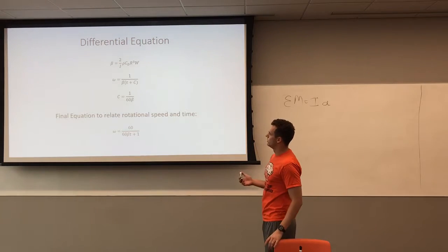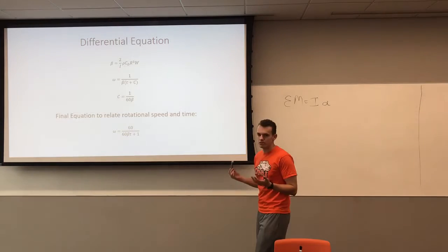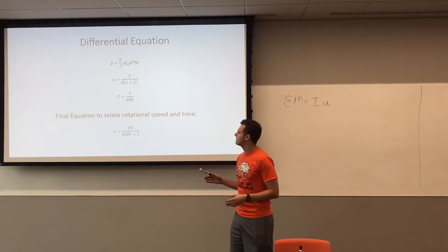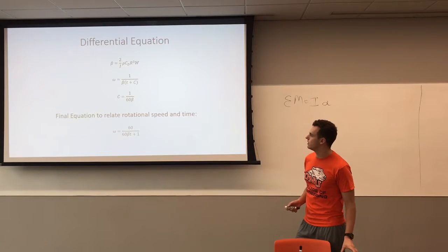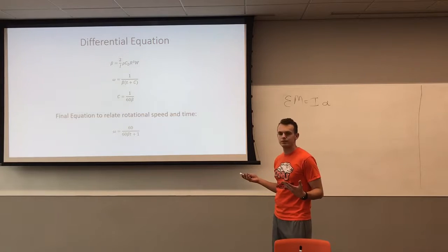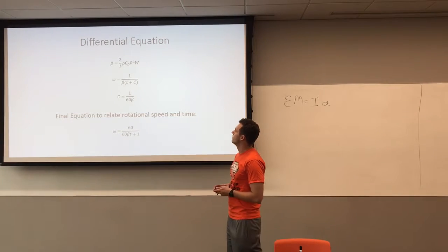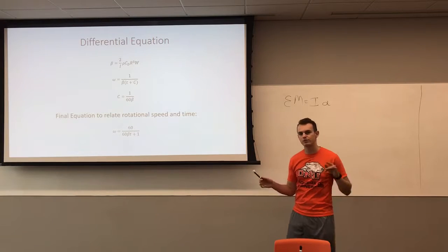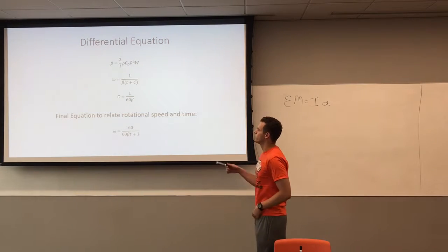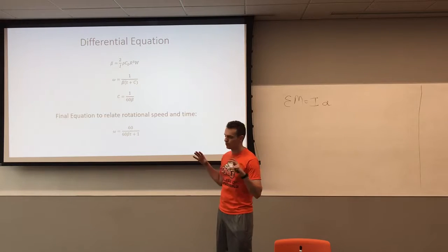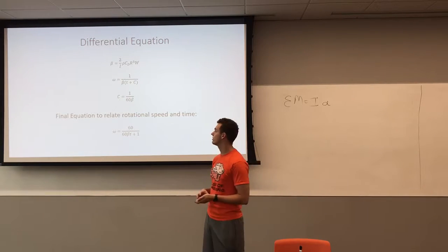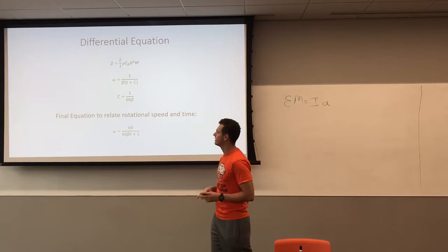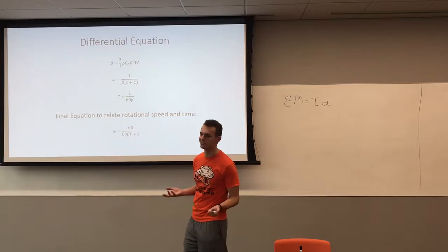Then in order to develop the differential equation that governs this motion, we will be replacing the beginning term of the force equation. We multiply by 3 for each blade, since there are 3 blades, which cancels the 3 off. Then we take the entire rest of the drag force term, without the omega squared, and put it into a constant beta because it's not going to change.